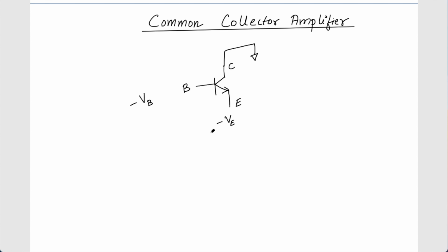The reason is I don't want to use negative potential here for biasing to make it a forward bias region. Or the other way you can think of it is that I'm adding some positive potential such that all the potential shifts up. This is another way of looking at it. What is most important is that AC wise it should be ground. It is not necessary that it has to be absolute ground. This is a very important fundamental understanding.